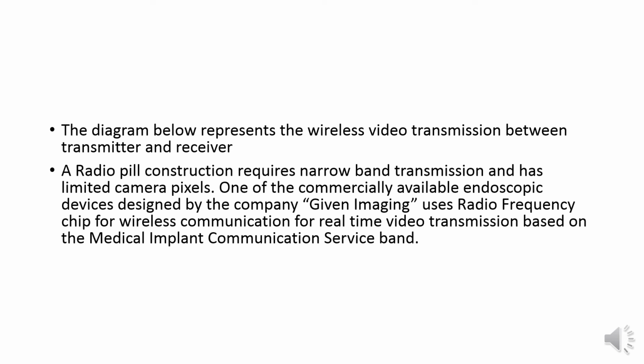If you are using the radio pill construction, it mainly requires narrowband transmission. So we have to use a limited camera pixel. With the limited camera pixel, we use a radio frequency chip for wireless communication. We use real-time video transmission, which is mainly based on the medical communication service band.